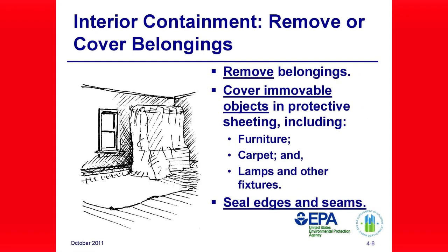Interior containment. Remove or cover belongings. When practicable, remove belongings and furniture from the work area. It is desirable to remove all objects from the work area, including furniture, rugs, and window coverings. Removal is the best option for protecting occupant items from contamination and for reducing post-renovation cleanup.